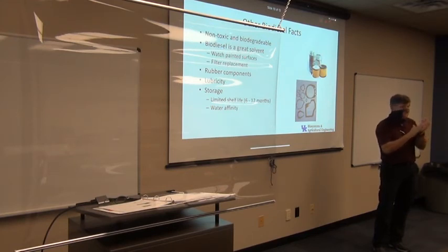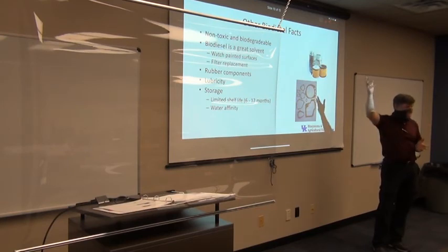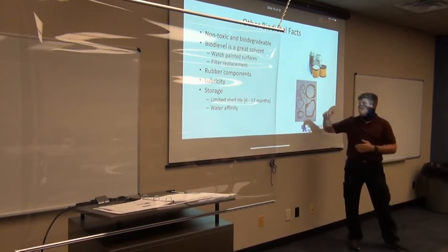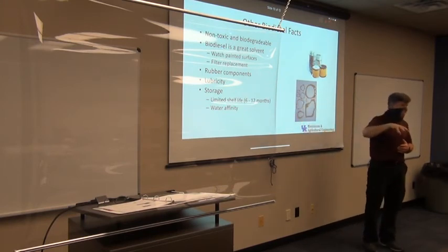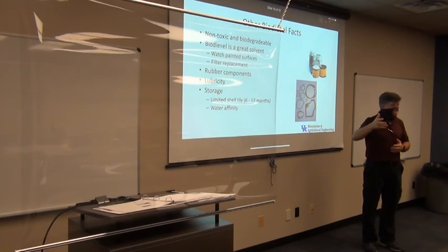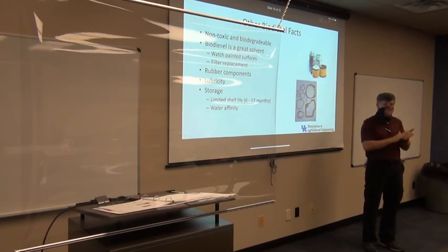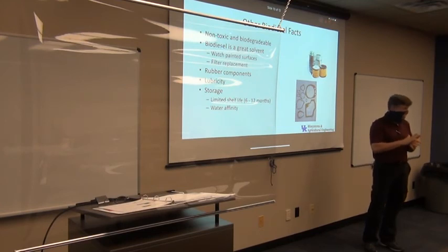wear pumps out. Well, sulfur, when you burn it, does bad things in the atmosphere, and so the EPA says, no, get rid of the sulfur out of the fuel. So now we've got to have something in our fuel to provide the lubricity that we need for those components in the engine. That's one of the reasons why you see most of our supplies with at least B2 to B5 percent biodiesel, to provide some of that lubricity back. And then it's biodegradable, non-toxic. So that's one of the good things that it does for us, it gives us that lubricity.